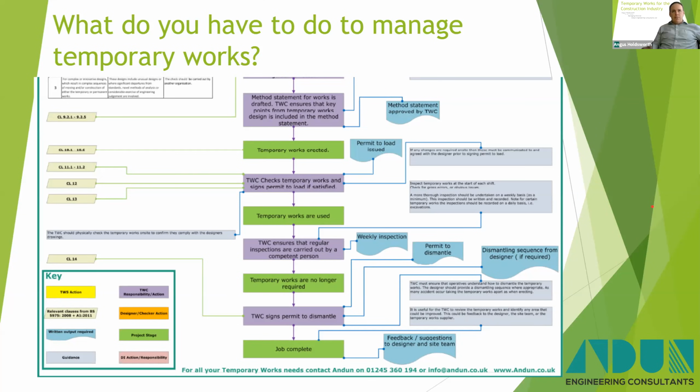In fact, this is some learning that we've had from going back, I don't know, 5-6 years ago, that we need to pay, and everyone needs to pay as much attention to dismantling as they do to erection of temporary works. It's almost like you've done the design, they've put it up, and then they're in a rush to take it down. And that's when we've seen more accidents than with the erection of temporary works.